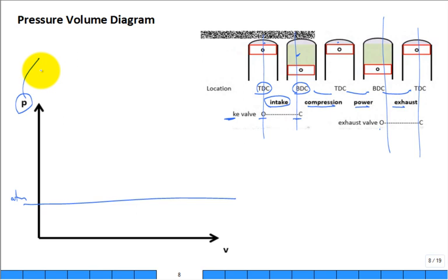Most of you run with your foot fully on the gas pedal, so it's wide open throttle, so there's no restriction in the butterfly, right? But if you're idling, there's going to be a restriction in other places in your intake. And so it's in a vacuum. As you're going from top dead center, which is a small volume, to bottom dead center, which then has the largest volume for that gas, it's going to be drawing it in under atmospheric pressure in a state of vacuum. And actually, that's how your power brakes work, right?